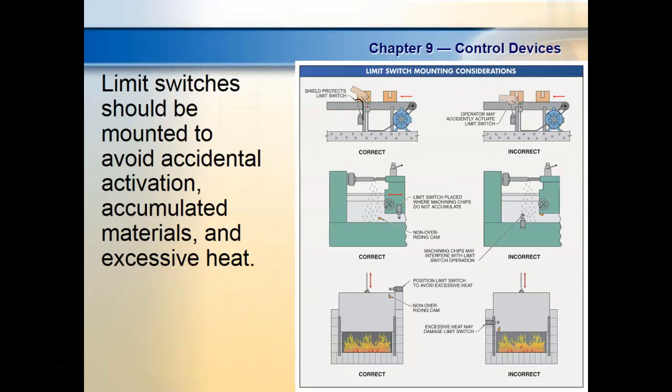Limit switches should be guarded to avoid accidental activation. Here they got one mounted under a lathe. Here they got one mounted at the top of the furnace instead of at the wall.